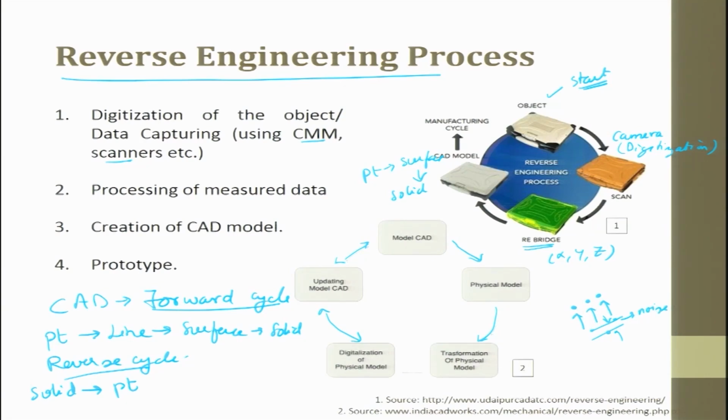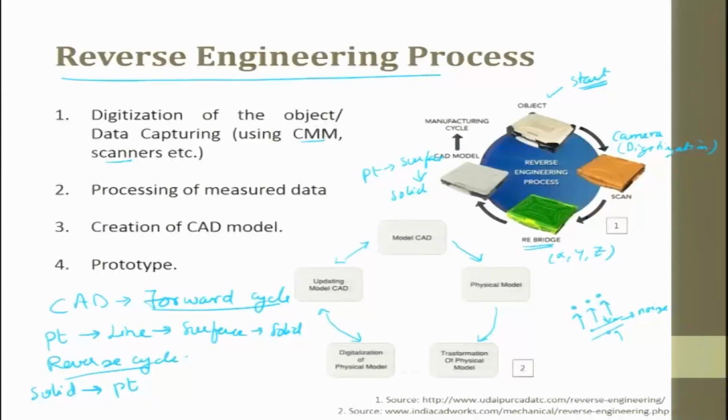You are supposed to get good data points which form an object, called a signal, and some random noises which are inbuilt are nothing but the error. These errors are because of internal reflection of the laser, or when you touch the data point, the probe slightly slides off, or if it is circular, or there is a depth which you cannot measure because the feature depth is very high, and very small features are there. So, then we have a lot of noise data to smoothen out.